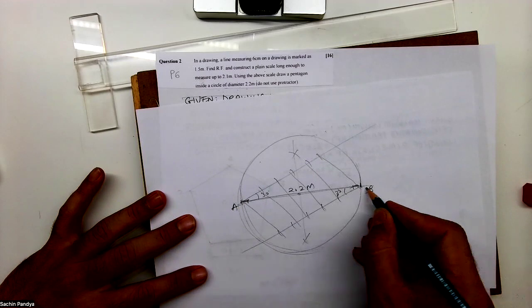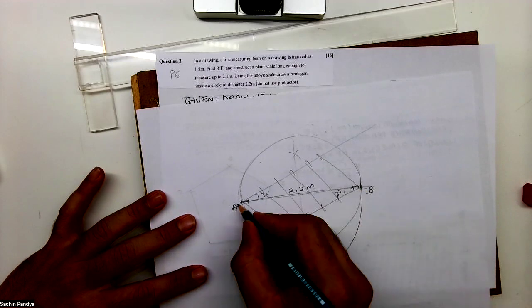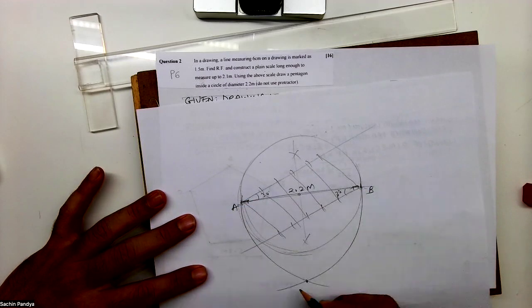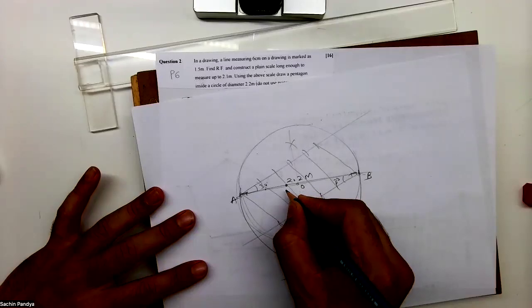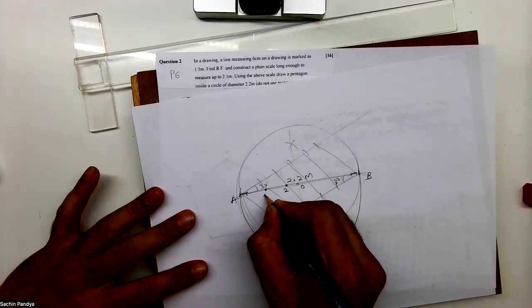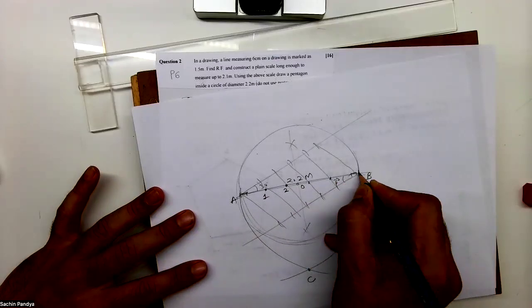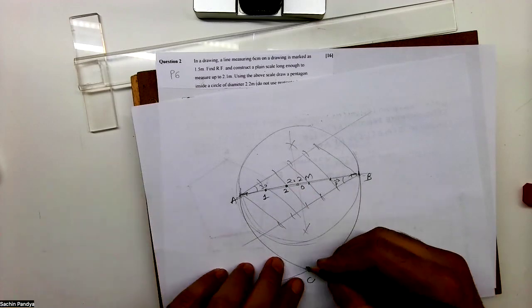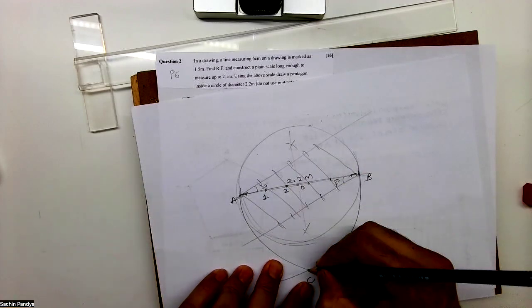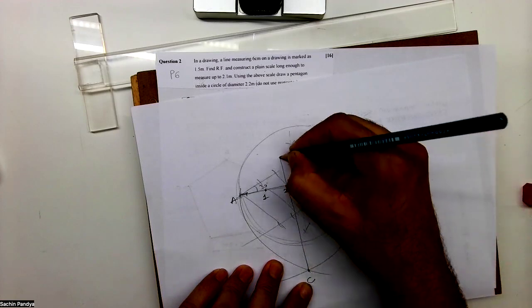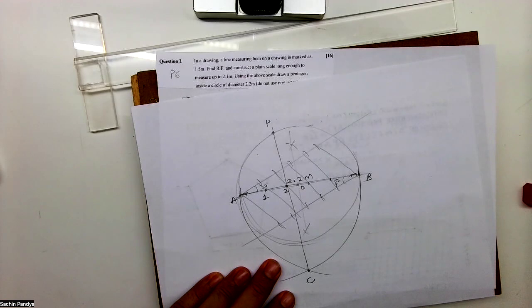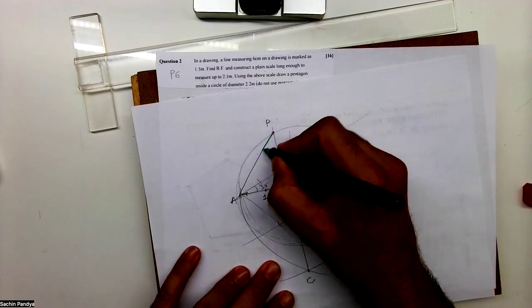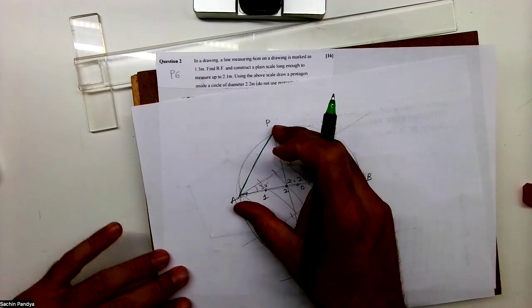Right? Then take A to B, rotate. B to A, rotate. We'll get point. This is O. This is C. Now this is point number 2. See, division wise, 1, 2, 3, 4, 5. Right? The point number 2. So draw a line passing through C to 2 and extend it. Wherever it will cut, that is P. So what you get, A to P is the side of the pentagon.